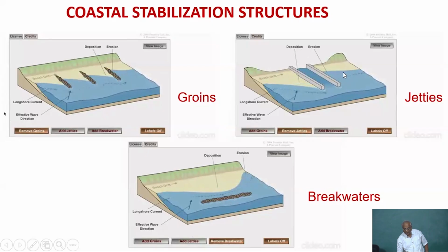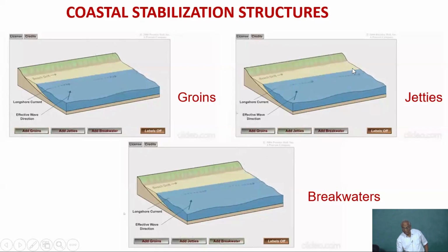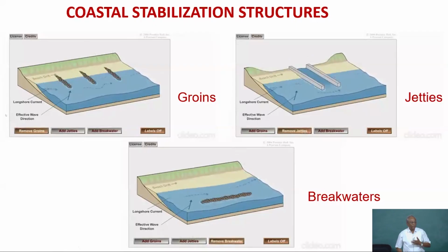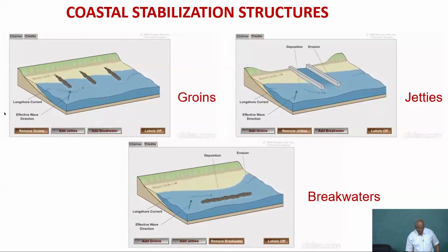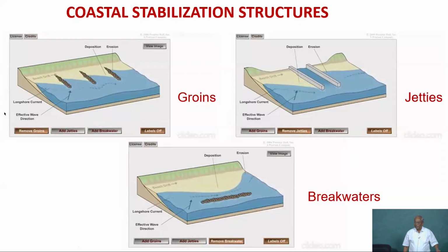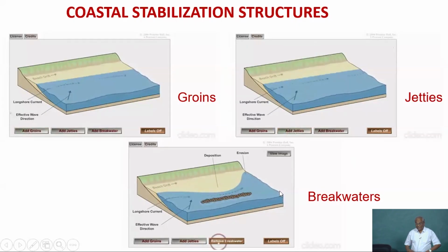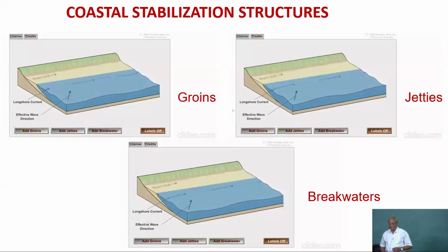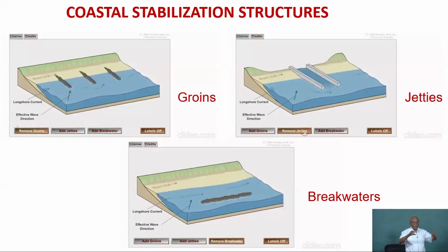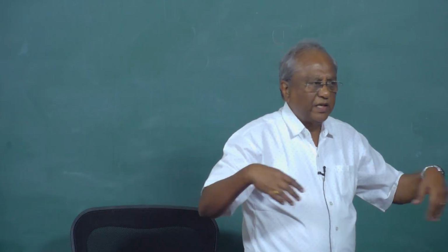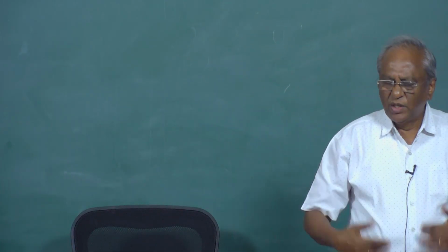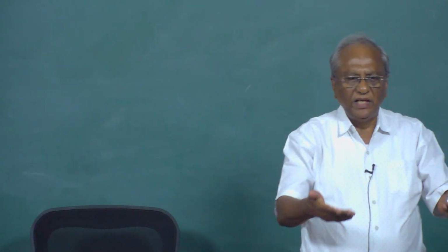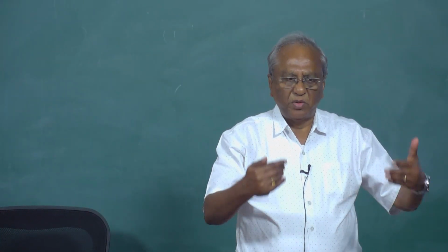So this will experience erosion. So probably in order to take care of that erosion, you might have to go in for a coastal protection measure, maybe with a small groin field, transition groin field. Or this is the one which is for offshore detached breakwater, which we have already seen earlier. So this also can be used as a coastal protection measure when you use a number of breakwaters separated by gaps. The main thing is diffraction of waves that is going to lead to the building up of the shoreline on the lee side of the breakwater, that is in between the breakwater and the shoreline.